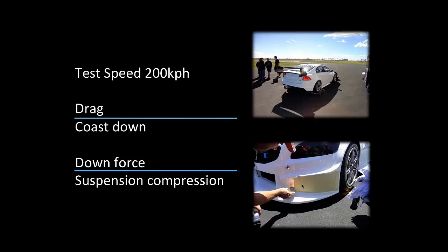So we do have mandatory drag and downforce figures we have to meet for the category in order to have our car signed off for its body development. So if you've got drag, put it at the back. That helps explain why we have that interesting deck lid extension that is basically trying to catch drag at the end of the day.